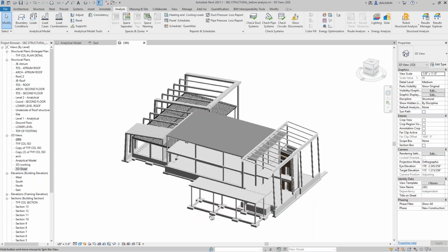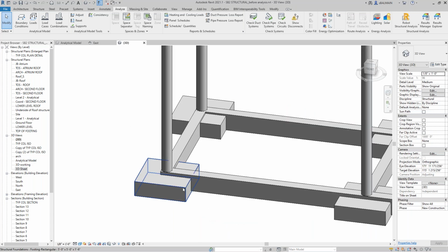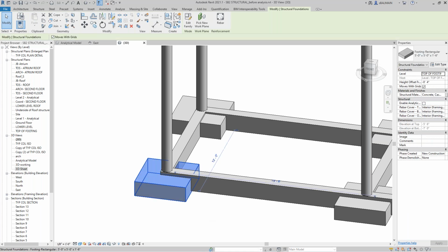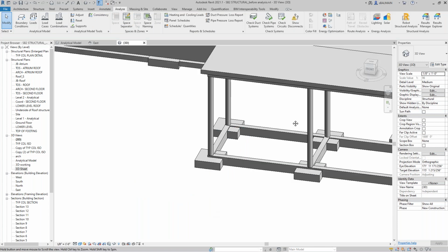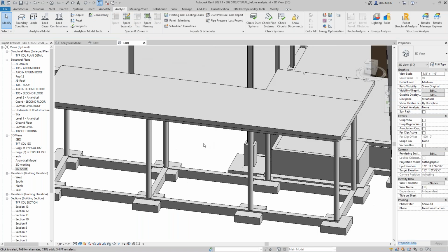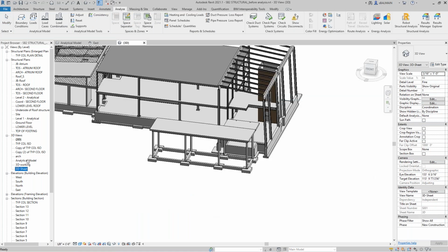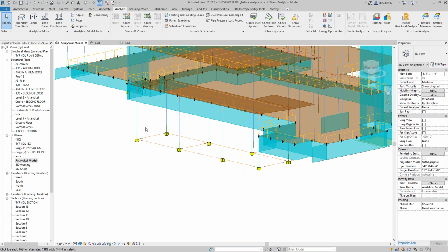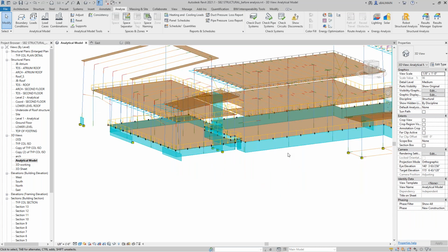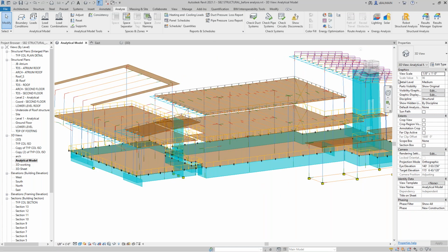a footing here. In fact, sometimes it's not really exactly at the center, and in Robot it creates a node, but not at the bottom of the column, or sometimes not at the good level. So after you can adapt, but it's not so hard. So here now I can look at my analytical elements, and here I can go to my result explorer.